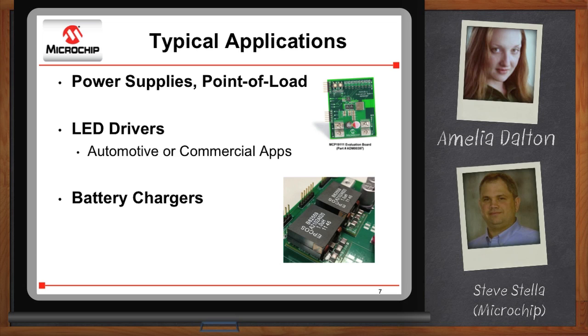Right. The flexibility of that digital interface allows you to modify the behavior of that analog controller to charge any type of multi-chemistry cells. So depending on your application, instead of programming in the analog domain with resistors, capacitors, setting set points for current limits, voltages, you can now just update tables in the microcontroller to get the voltage set points, current set points, and really makes it easy to design battery chargers. And then there's multi-rail power supply applications as well, so these can be combined together. There's master-slave modes that allow them to communicate with each other so that you're able to manage the input power as well.